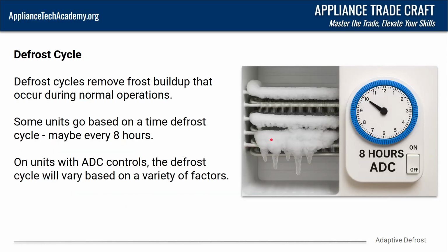Now let's talk about the defrost cycle itself. The defrost cycle removes frost buildup that occurs during normal operation. Some units are going to go based off a timed defrost cycle, maybe every 8 hours, 12 hours, 24 hours. It really depends. And then on units with adaptive defrost controls, the defrost cycle will vary based on a variety of factors.